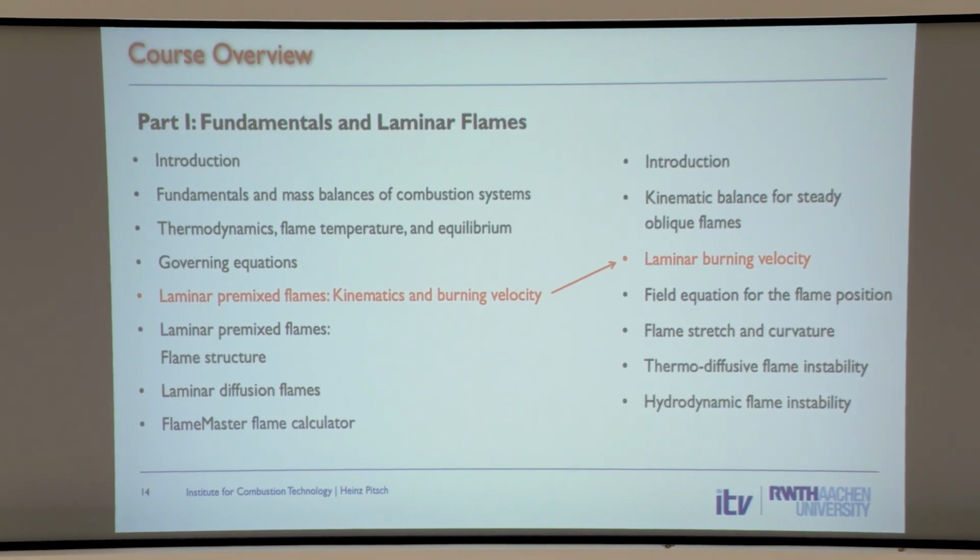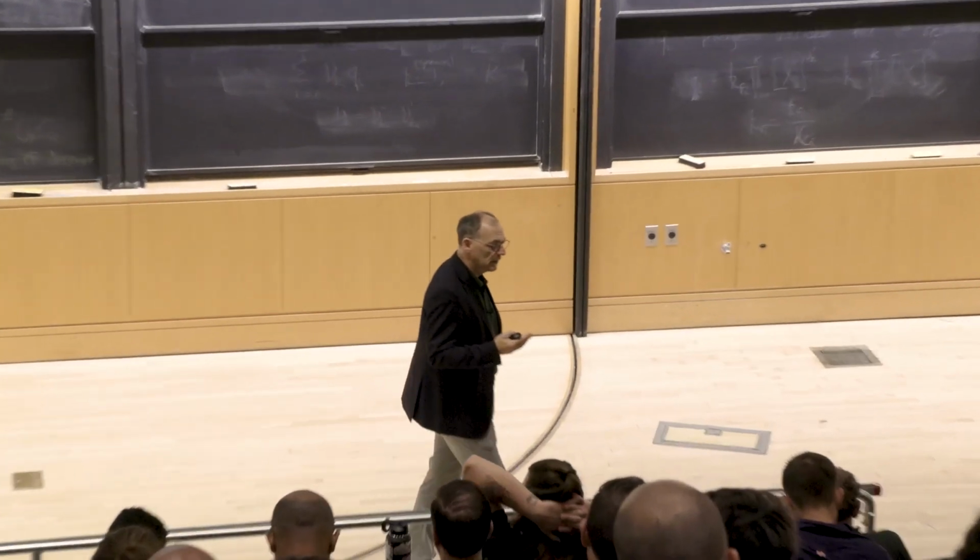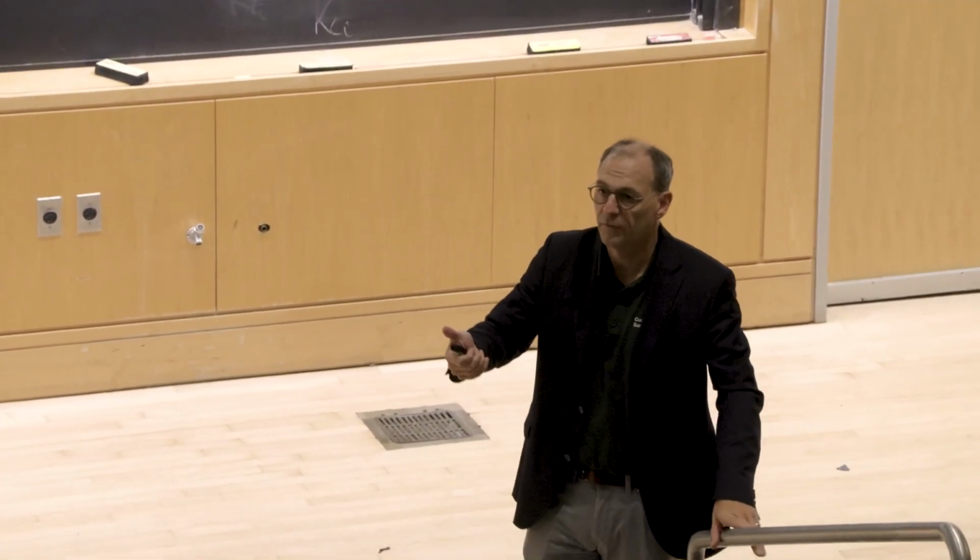Okay, so we determined burning velocity, that's a really important quantity that we need to worry about. Burning velocity, by the way, is very important for safety. A fuel that burns very slowly is much safer than a fuel that burns very fast. So I mentioned we do some work to look at safety for refrigerants. The safety standards for refrigerants are really based on the laminar burning velocity, okay? So they say